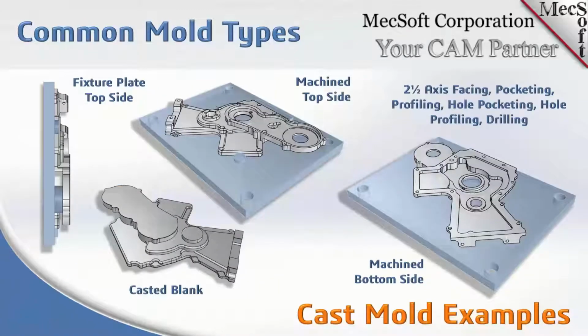Okay, here's another example of a cast molded part where, again, you have to have a blank. So we have the casted blank over here on the left side near the bottom, and that needs to be modeled and created. Now, in order to create this blank, you can also create a prototype mold with a cavity and core in order to mold the blank. The blank doesn't have to be obviously as accurate